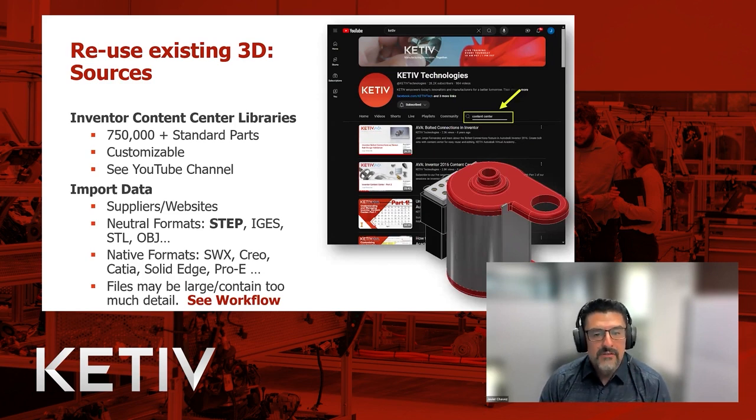If you're going to get data from vendors or suppliers, you're going to have to import that data from somewhere. If you're fortunate enough that they have the same tool, they could just bring it in, right? But in a lot of cases, you're going to have to work with neutral formats, right? Exchange formats like STEP or IGES, or you can see some of the lists there. STEP is preferable. It's probably one of the more common ones. And for some reason, your customer has a different tool. They can send you their native format, their native SolidWorks files, Creo, et cetera. In a lot of cases, Inventor can work with that directly.